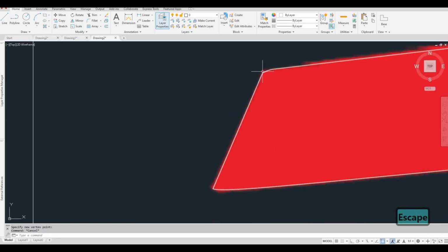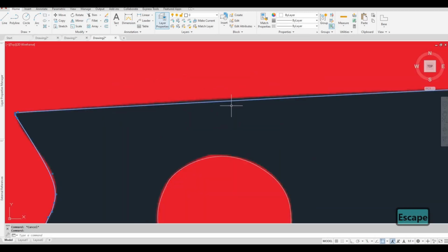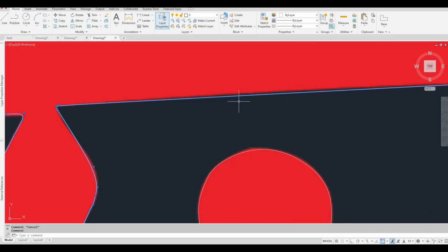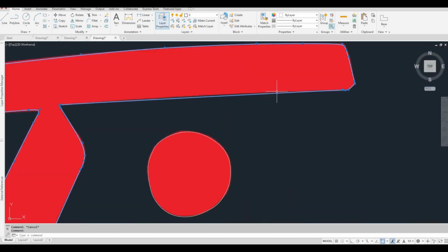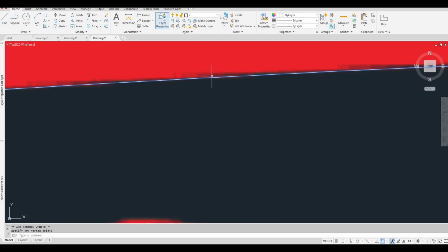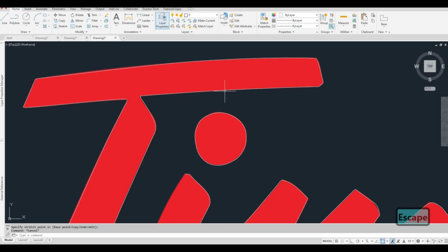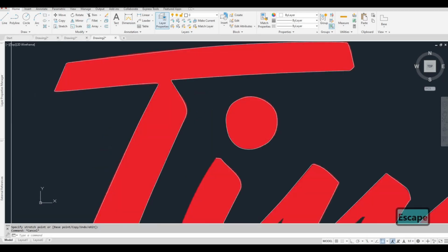As you can see, we improved at least this one, and because this is a spline, you can select it. If you added a lot of vertices, so for me, I should have added a lot of vertices here, not just a straight line, so that I could show the curve. But as you can see, I can just add it right now. There you go. Now you can grab that vertex and push it upwards. It will still create that curve that you want.